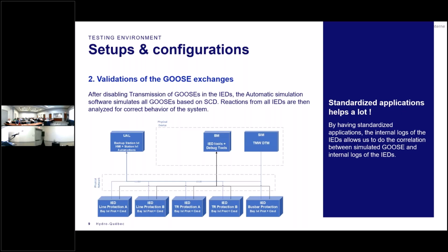So when importing the SCD within DTM, we were able to identify which signals could be creating behaviors in the system. And based on our data model that we standardized across the whole system, we were able to identify which signals and which behavior was associated with each signal and simulate them, so that based on the reaction of the IEDs and the time tag of the different signals, we were able to validate the correct behavior of the different components of the system.